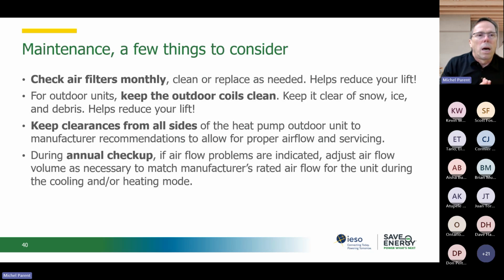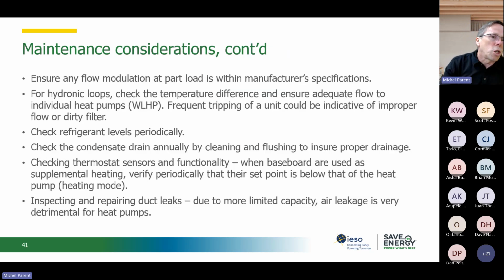There's more here. You want to make sure that you don't lose too much air through your ductwork because, again, the capacity of heat pumps is more limited than what you're used to. So you want to minimize any kind of losses. Obviously, you'll have to clean the coils, which you would always do. The condensate drains have to be cleaned, probably more than once a year. So there's a bunch of maintenance considerations that should be included based on the type of heat pump you select in order to maintain that efficiency.